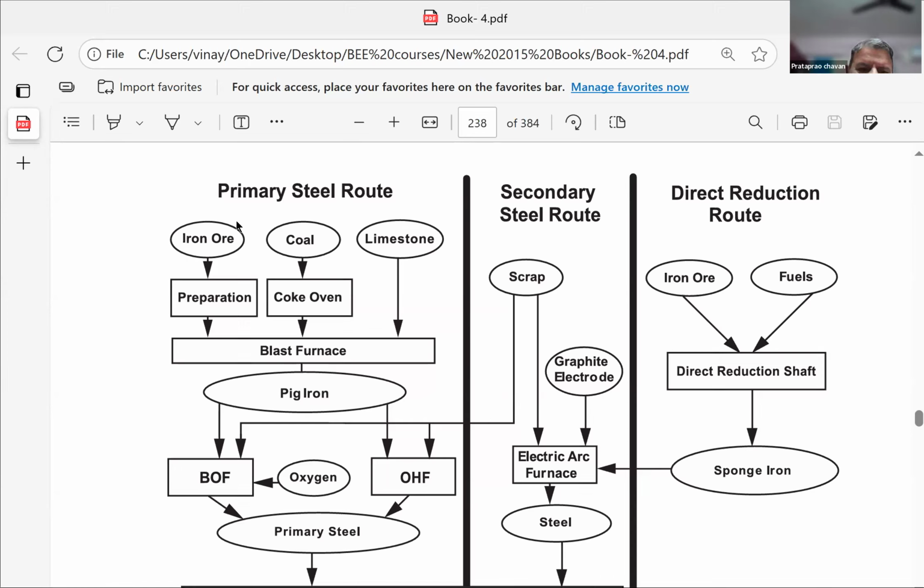The mining product that is coming out of the fossil from the earth surface contains a lot of impurities. There is dust, dirt, other elements mixed, and also organic matter, a lot of things. It comes in the form of iron ore. Then this iron ore, you have to prepare, you have to use some auxiliary equipment. Prepare means remove the dirt and dust through separation methods, mechanical separation, dry methods. Then whatever purified iron is given to the blast furnace.